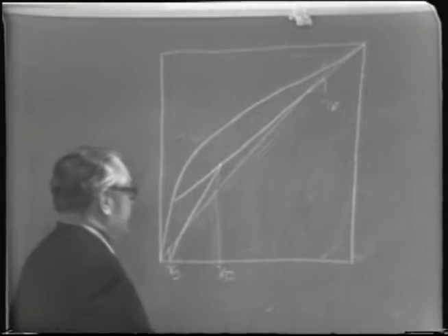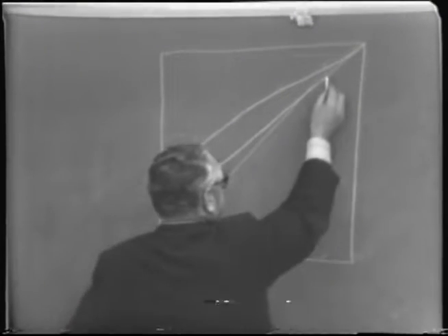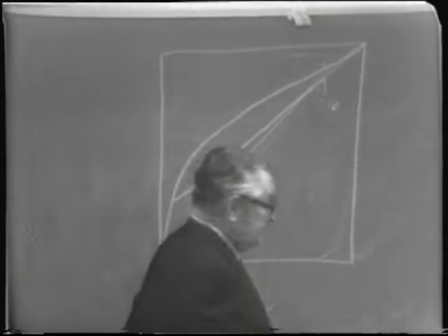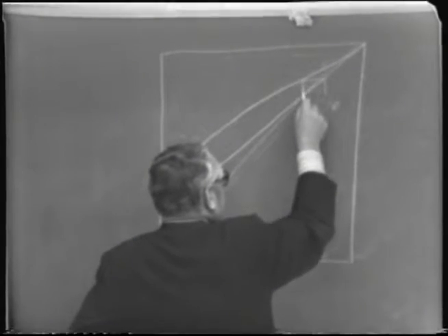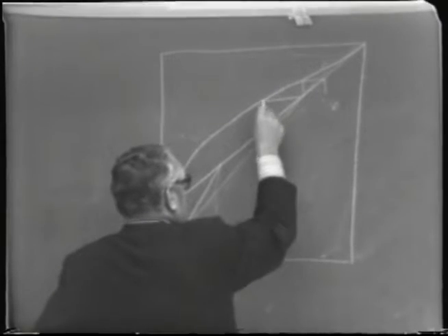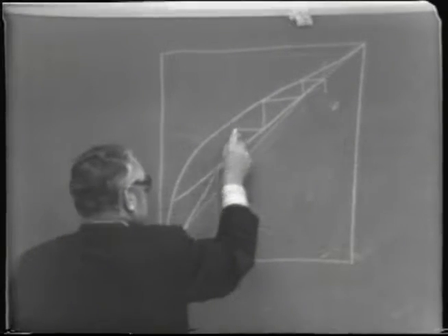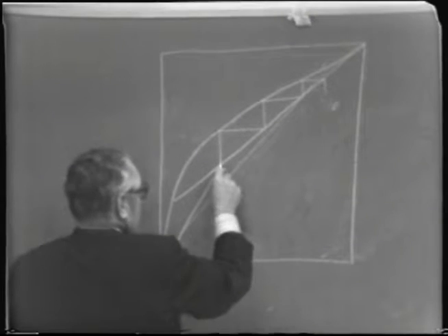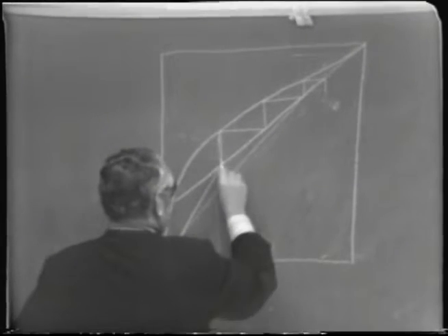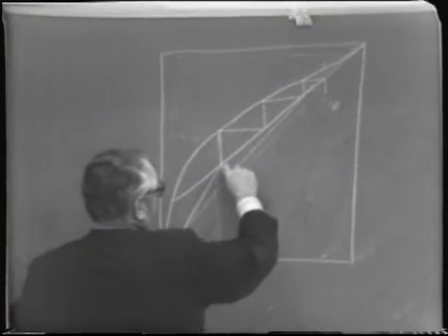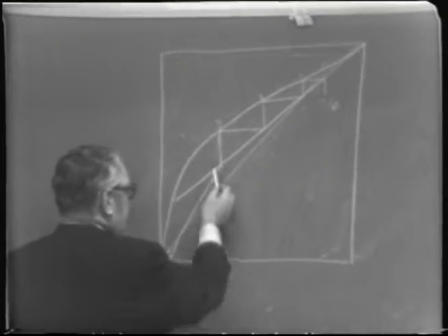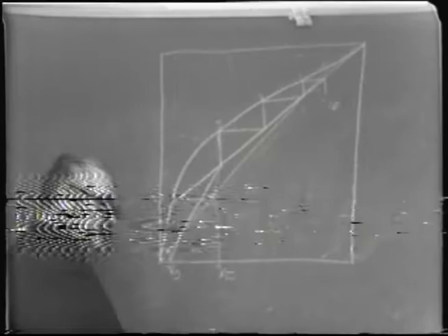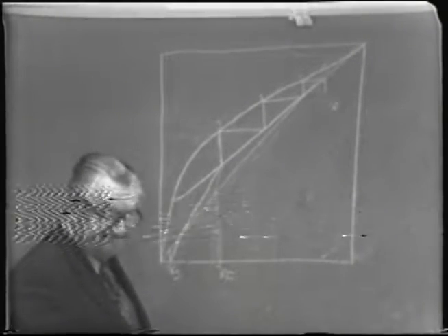All right, now then, ideally, and starting from the top in this case, for convenience, we'd have about this many steps here: 1, 2, 3, before we'd cross over to the operating line for the stripping section.